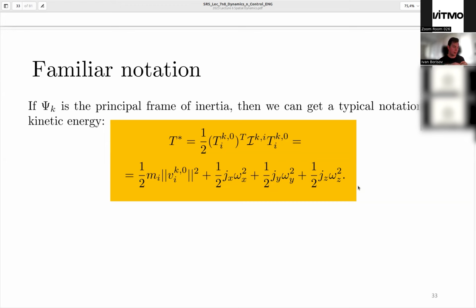since the kinetic energy of a system is just a sum of the kinetic energy of each part. And then we come up with a general equation for a sum of infinitesimally small pieces. And then in order to make the equation simpler, we have rewritten it so that it depends on twist, and twist is the same for each point, and we can take it out from under the integral,